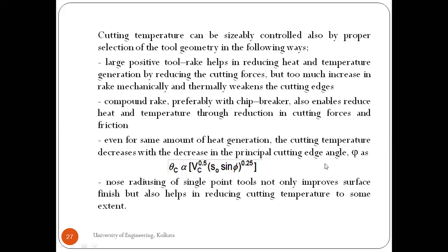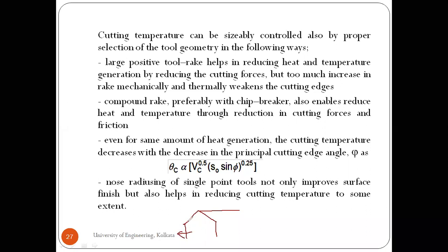Nose radiusing of a single point cutting tool not only improves the surface finish, but also helps in reducing the cutting temperature to some extent. We have also discussed this once, I'll quickly reiterate it here. Suppose this is your tool, and this tool is moving in this direction relative to the workpiece.